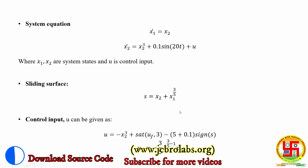Whereas we have differentiated and set s dot equals to 0, and we have calculated the u equivalent part, which is minus x2 cube and minus 0.1 sin s, and saturation with limit 3 is used because of the singularity problem present in terminal sliding mode control approach.